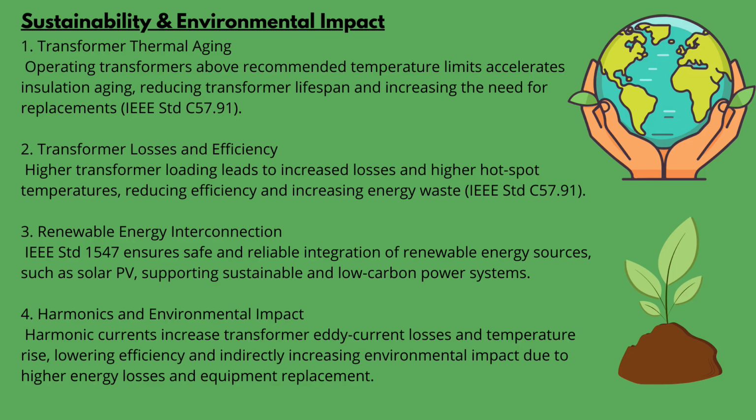Number 3. Renewable energy interconnection. IEEE standard 1547 ensures safe and reliable integration of renewable energy sources such as solar PV, supporting a sustainable and low carbon power system. Number 4. Harmonics and environmental impact. Harmonic currents increase transformer eddy current losses and temperature rise, lowering efficiency and indirectly increasing environmental impact due to higher energy losses and equipment replacement.